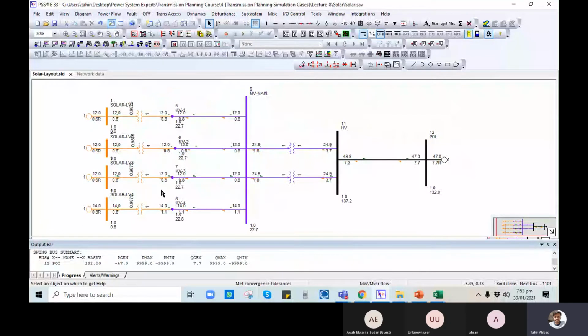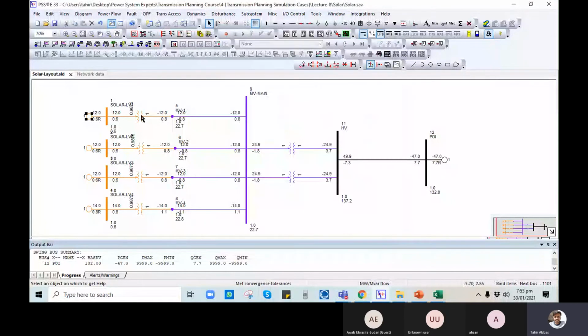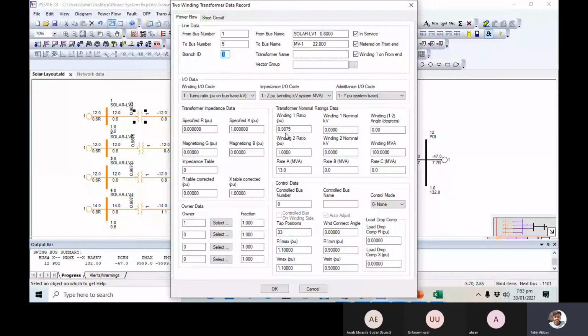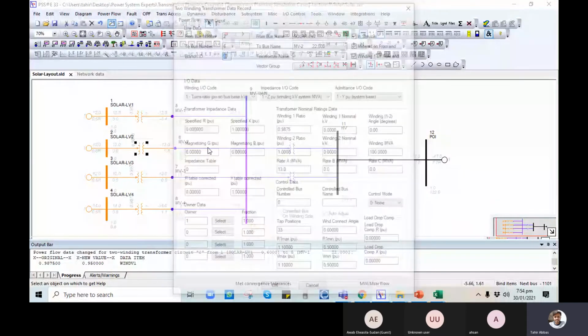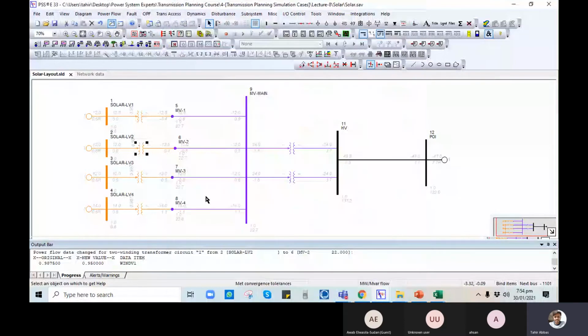And also the next thing is that the system still is producing 7.7 reactive power. So for that purpose, look at this value now. It means that this generator has a maximum capability of 3, so it means it's providing only 0.6. So for this purpose, we are reducing its tap, and let's see now, the reactive power supplied by this generator will be increased by all these inverters basically.